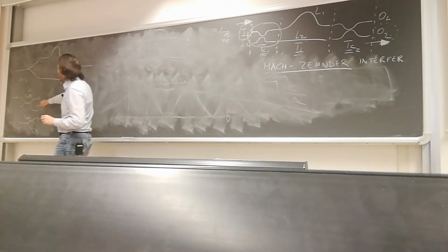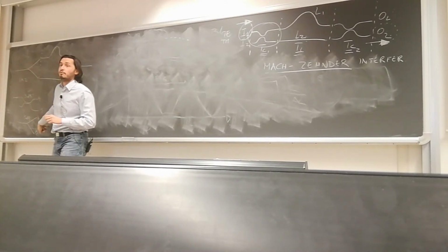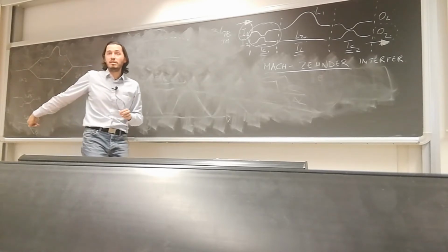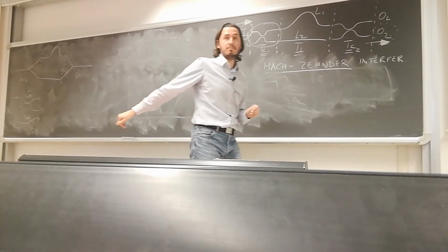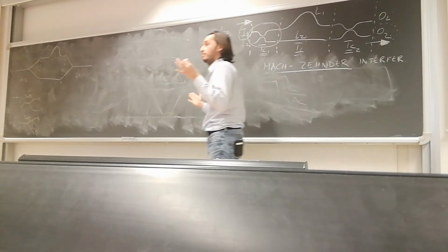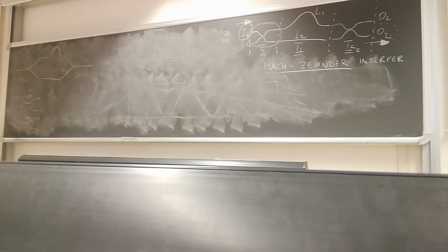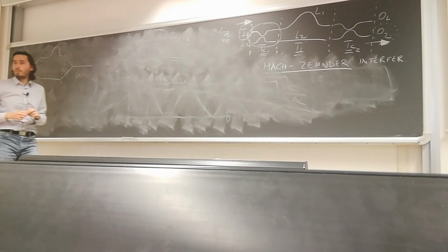If I write here, this is the power, okay? 50-50, 50-50. Some information is missing. And the missing information is the phase. Always. It's a nightmare. So, is there any difference between the phase between these two guys in a 3 dB splitter and these two guys in a Y branch?